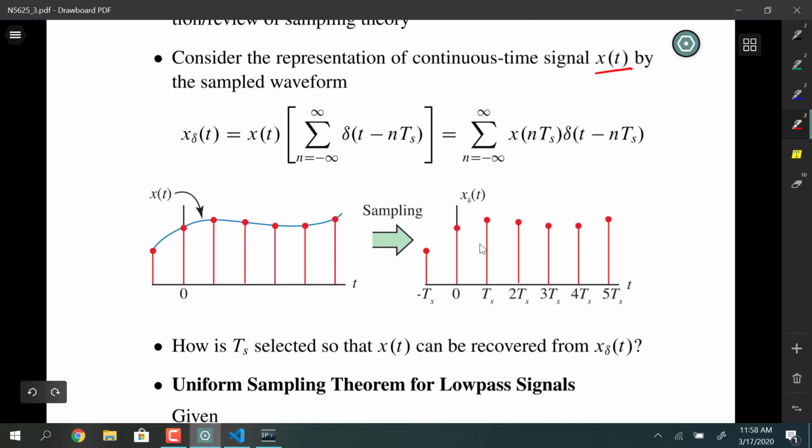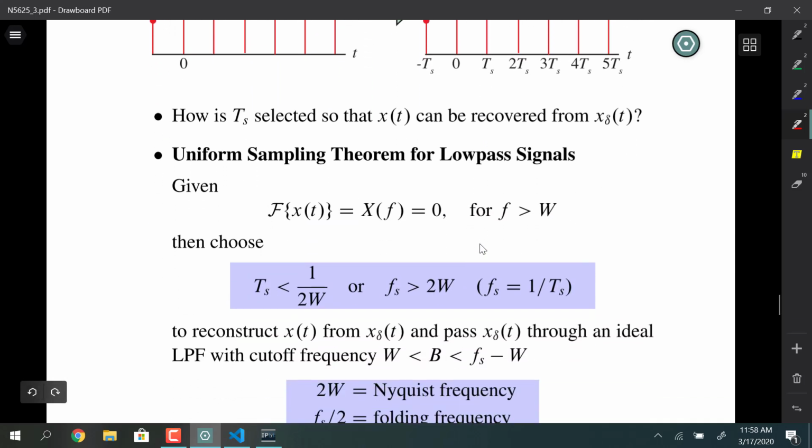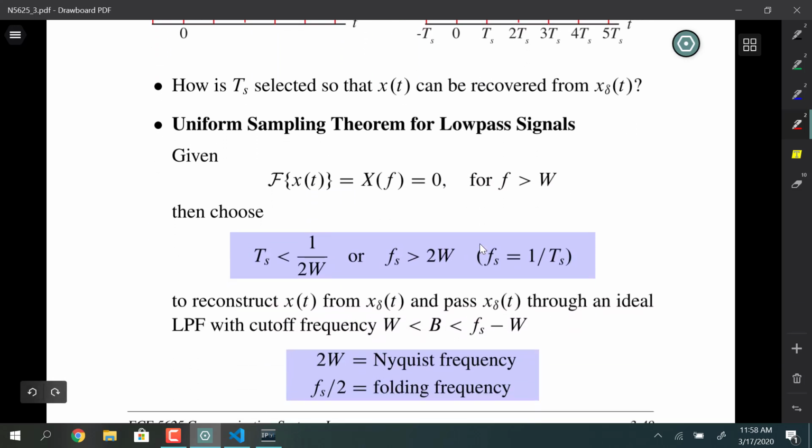Like if it's pulse code modulation, that is our primary example that we're headed towards, but it could be other pulse modulation types. But some means of converting an analog signal into samples and then representing each sample with a digital word is the more common scenario. So basic sampling theorem is low-pass signal.